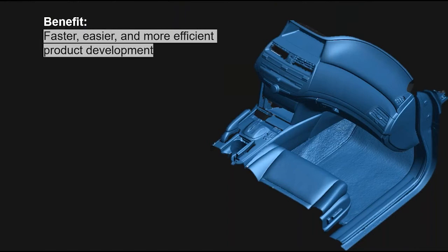There are several benefits to use a 3D scanning technology. First, the acquisition is done quickly. Second, the surfaces are measured completely and there is no missing data, as we can see on the picture on the slide. Missing measurements often cause delays in the product development, especially if you do not have easy access to the car model or the part. The measurements are also more accurate, which will lead to a superior design quality and a perfect fit that will differentiate the part manufacturer from competition.